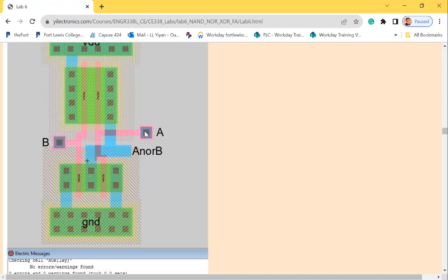But however, if I have a metal 1, a poly to metal 2, I know there isn't that kind of thing. But if there's a poly to metal 2 contact, which means I can directly drill a hole from poly to metal 2, can I keep it close to the metal 1 trace? I know it doesn't exist, but if there is one, maybe in a different process, yeah, but not this one. Are you getting my point here?